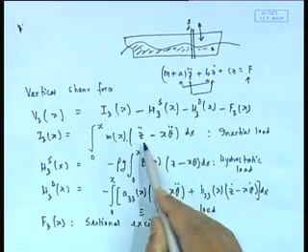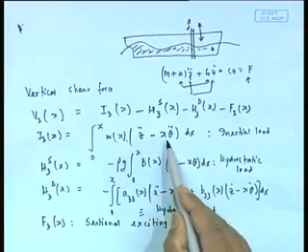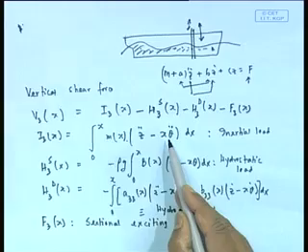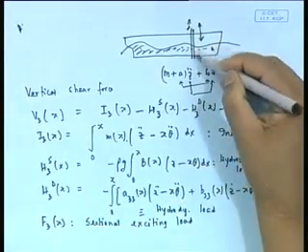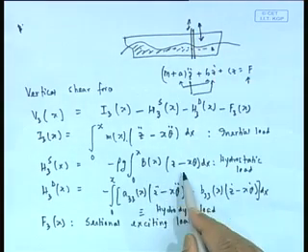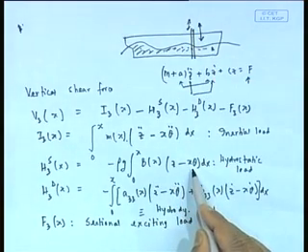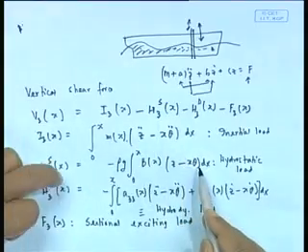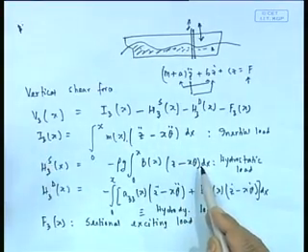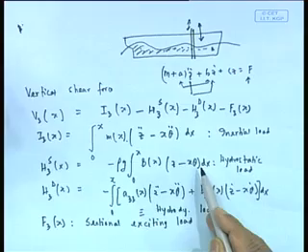That is what we have done earlier, isn't it? Z minus x theta is the vertical displacement, and therefore the acceleration with the double dot. Then remember, because it is going up and down, I have a displacement given by Z minus x theta into local beam. That will give me my so-called AWP into Z, the hydrostatic restoring force, additional part. Remember, the additional part, because the rest is balanced with the mass part, so we are not taking that. This is the additional load coming because of ship motion. So this is my additional part, unbalanced between the buoyancy and the sectional buoyancy.